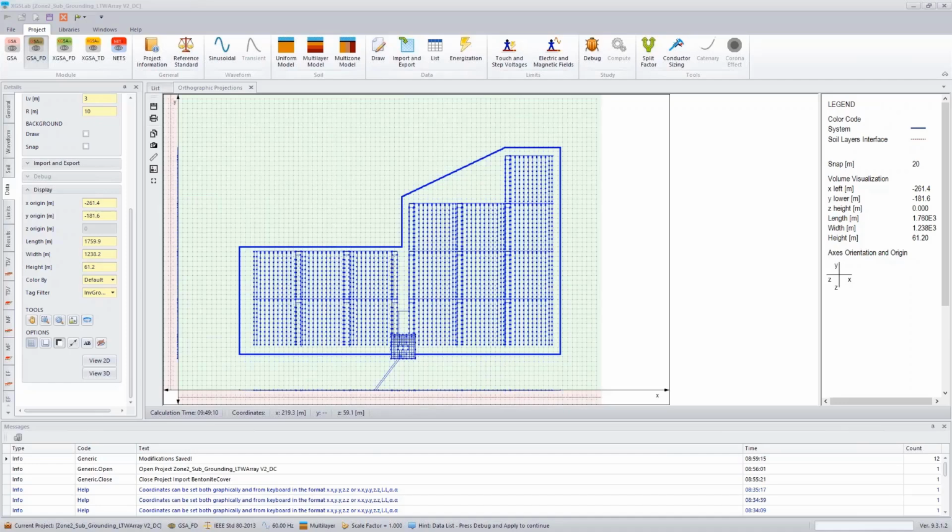Another individual asked, if you're starting to hit up against your software's capabilities as far as how many elements you can model, you can start reducing the density of those auxiliary grounding systems to lighten the computational load. That's one way to approximate it, and it generally should result in a more conservative analysis because you're reducing the amount of grounding system that's in your model.